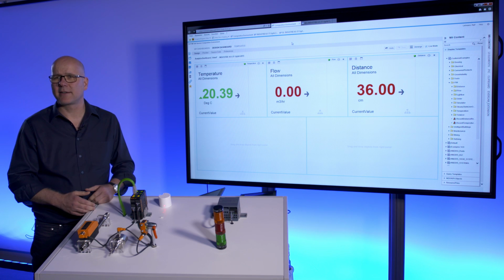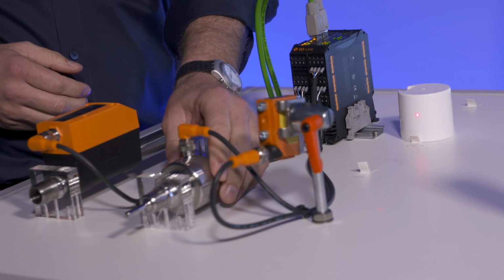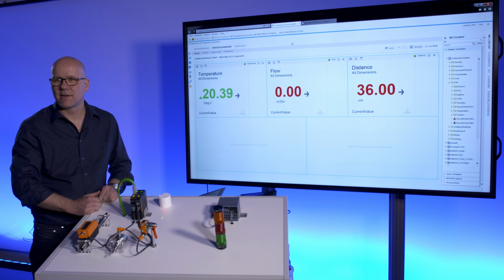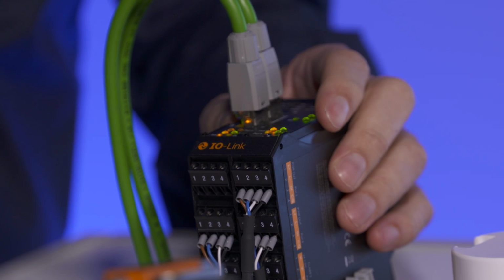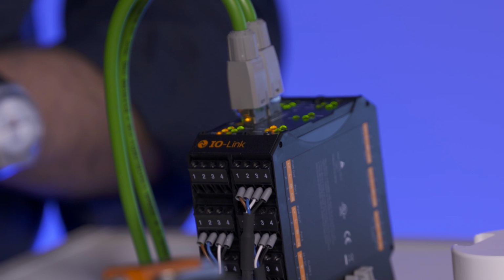We have three smart IFM sensors: a flow meter, a temperature sensor, and a laser distance sensor. They are connected via I/O link protocol to the AY1020. This box sends the values to the connectivity port, which includes direct communication to an agent in sub-plant connectivity. The update parameter is set to 3000 milliseconds. With the connectivity port, all IFM sensors can be connected, but also sensors from other vendors are supported.